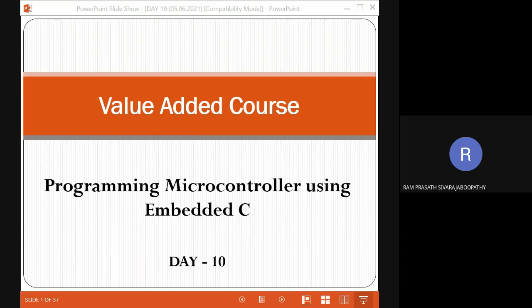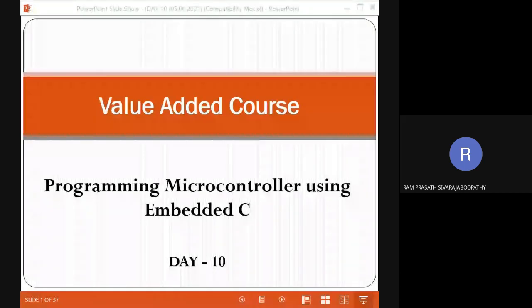We need not do the digit enabling and disabling process or keypad scanning process. But that is mainly meant for display devices only. You cannot interface any kind of keyboard to that. It is mainly meant for interfacing either an 8x8 dot matrix LED or an 8-digit 7-segment display.